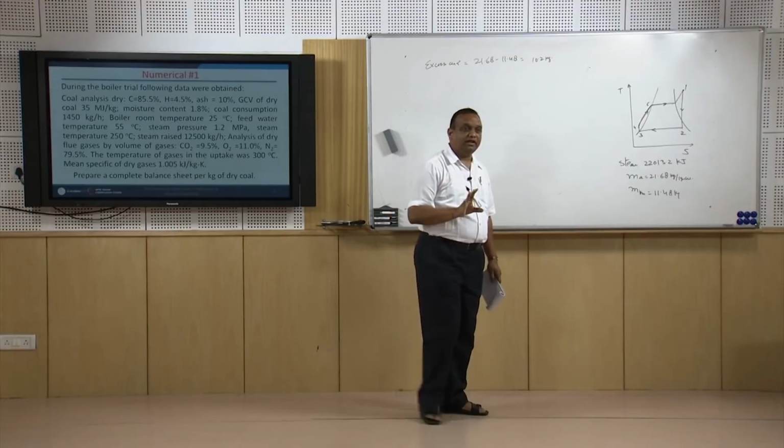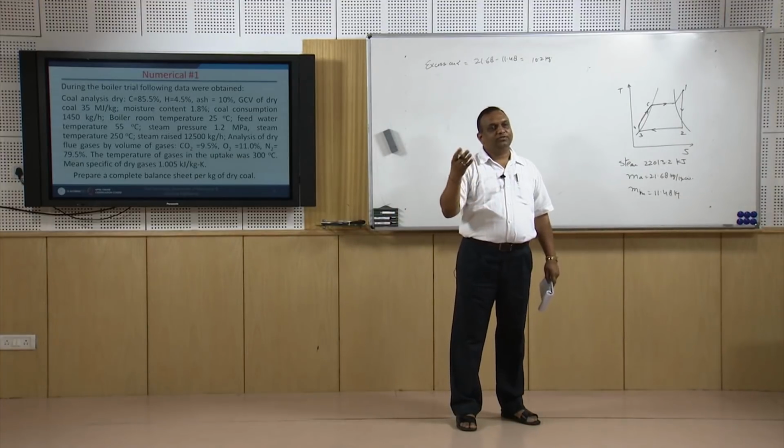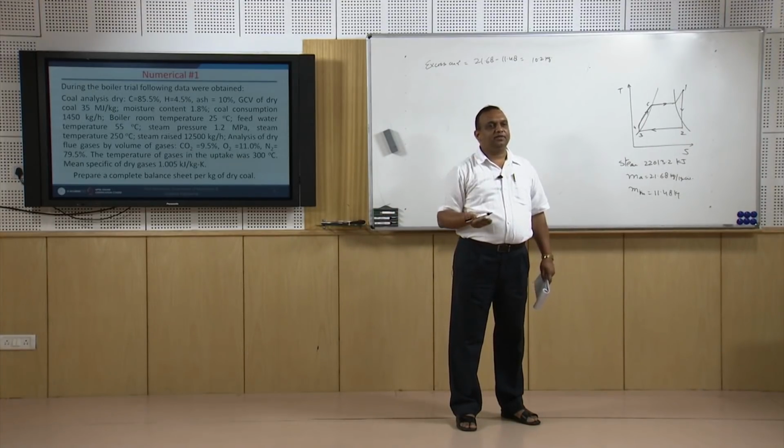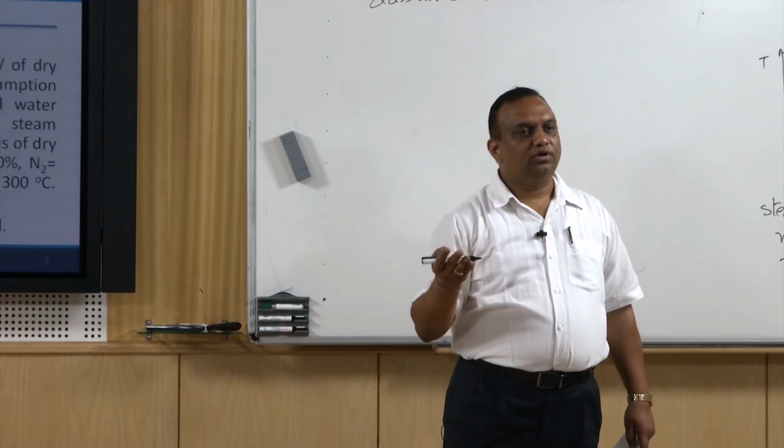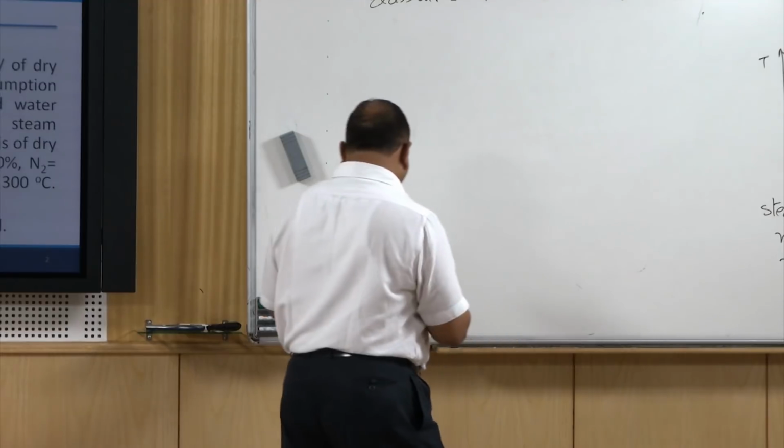We are calculating everything per kg of coal, because in the balance sheet we have to give values in terms of percentage, so finding all the values per kg of coal will serve the purpose.